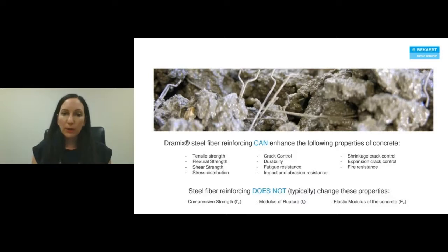However, even though fiber reinforcing and specifically Dramix provides all of these excellent benefits, it's just worth noting what it doesn't do. We do not typically account for any improvement to the compressive strength, right, your F'(C), or the modulus of rupture, or the elastic modulus of concrete. These are properties of the concrete specifically, and so you would expect those to remain unchanged.